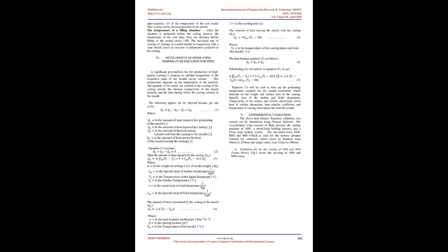10-11. Determining the optimal process parameter setting will significantly improve the mold yield, output ratio of metal, shorten the manufacturing period, and save energy and resources. During the injection of molten metal, the flow inside the shot sleeve before the plunger should be laminar. If the speeds and the injection pressure are not set properly, the flow of metal will be disturbed and convert into turbulence, and there will be a possibility of formation of porosity during the process.